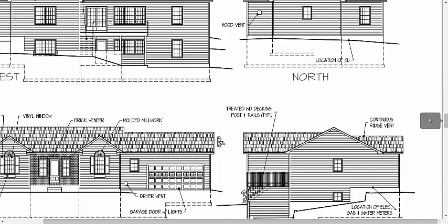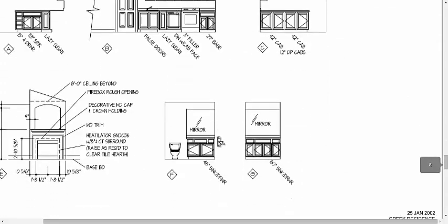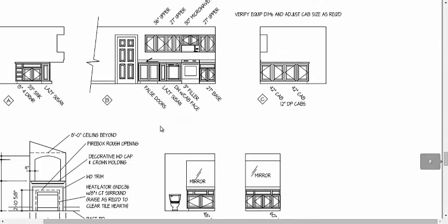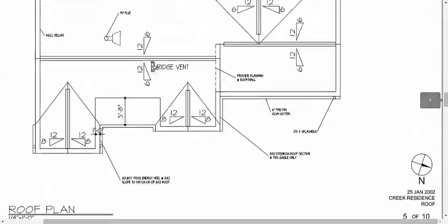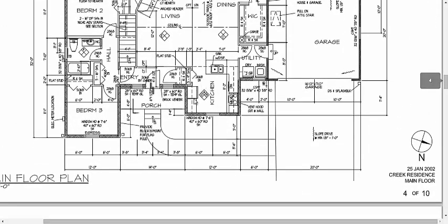Let's go find out. So let's go down to interior elevations, right here, okay? And we want to find letter B. Well, sure enough, we're looking at the stove, the microwave, dishwasher, some cabinets. It's even wide enough, the view there, that we can see even the sink sitting there. So if we go back to the kitchen, and you guys can kind of flip back and forth if you need to, that's the view we're looking at. So if we looked at A, we'd be looking at the sink. If we looked at D, we'd be looking at the fridge.